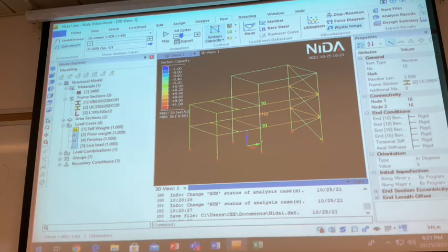But anyway, according to this project, you need to base on the linear analysis and then based on the linear force distribution, check and do your calculation. Yeah. Just because linear analysis cannot consider the nonlinear effect, you need design formula. You need design formula to help you to make sure it's safe. Otherwise, you just rely on the computer program. But when you want to rely on the nonlinear program, sometimes you will encounter the divergence problem. For the divergence problem, this sometimes is difficult to solve. Okay. Yeah, so they have a good thing and a bad thing.